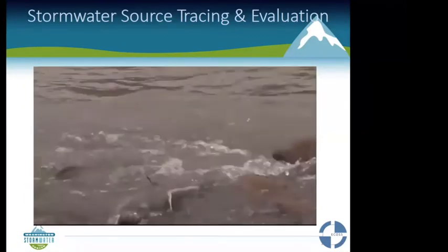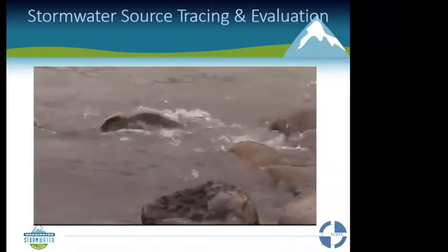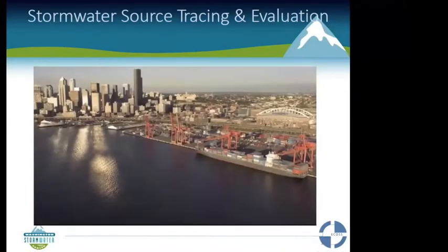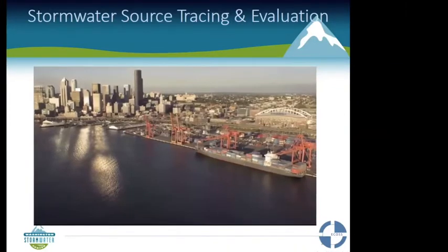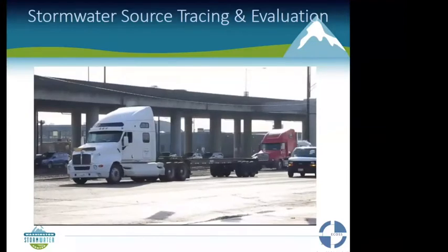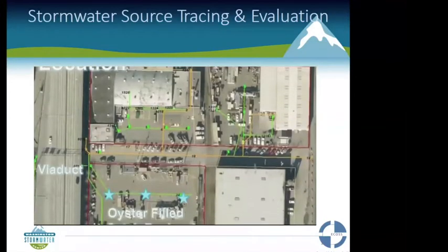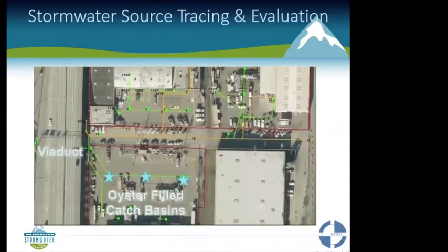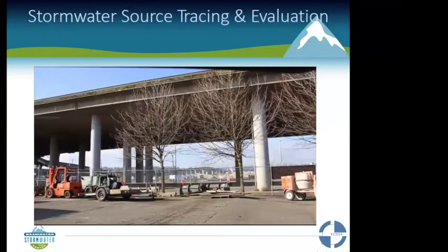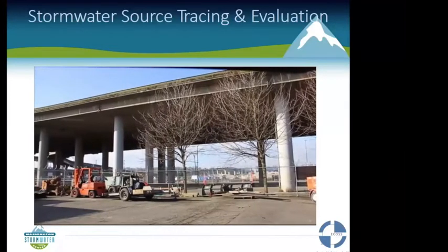Even at extremely low levels, copper can affect fish and other aquatic life. The Port of Seattle was having an issue with copper levels at their Seaport Maintenance Facility. By doing extensive source control and tracking, they found that an average of 300 parts per billion copper was being deposited onto their property from the Alaska Way Viaduct. They suspected that their proximity to this major freeway was a source, so they built the Guzzler to find out.